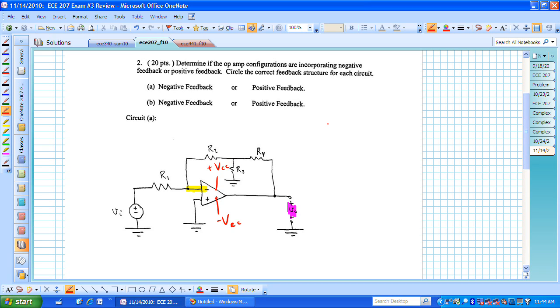And even with negative feedback, we can have saturation, and we will go towards the rails, either positive rail or negative rail, for V0, and not actually achieve the V0 that we would like to think we were getting based on the externally connected parameters around our op-amp, which in this case we have 4 resistors, R1 through R4, that are around this particular op-amp.